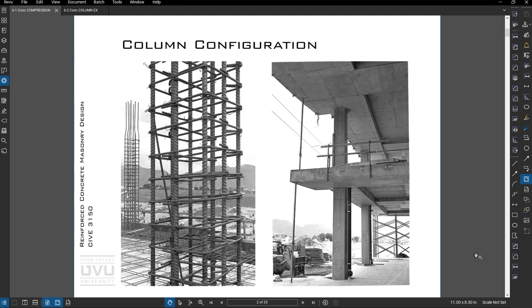On the left here we have a rebar cage, so vertical bars and then the ties which keep those in place. You can see a bend up here, so the column form is going to step to a smaller size. This is a finished floor or a couple finished columns with kind of a shallow beam type system. These types of beams are pretty inefficient, but sometimes the floor to floor height constraints drive beam sizes more than the beam efficiency.